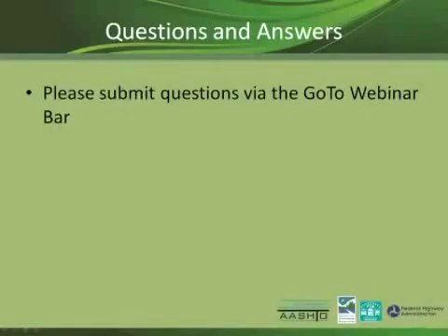Another question for Lee is how did you bid your media filter drains? Itemized or lump sum, and then were there any savings on how you did it? It depends on the design build or design bid build. If it's a design build project, I think we bid the whole project as a lump sum contract. So sometimes it costs like a couple hundred million for the entire project. If it's design bid build, I see people bid differently. Sometimes they itemize the items, or sometimes they bid by a linear foot. And if they bid by a linear foot, they have to have sort of a detail of what would be included in those linear feet. Okay.